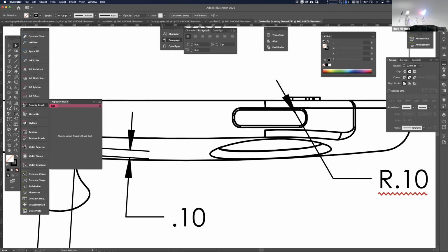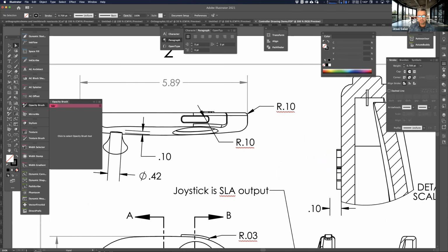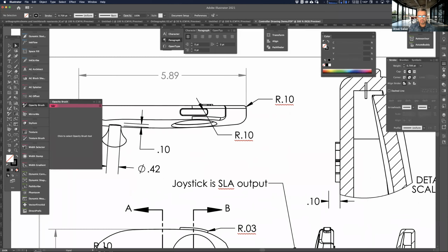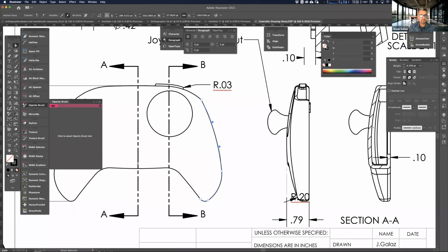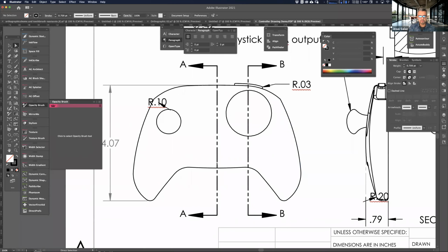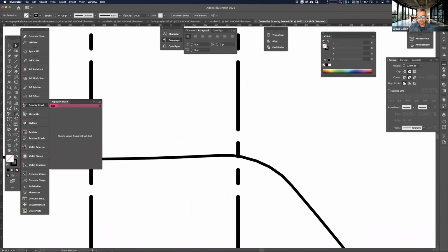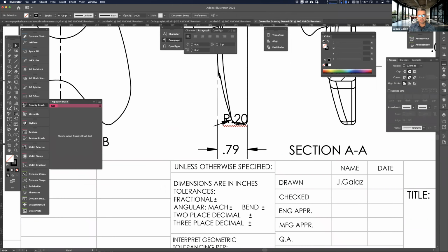So yeah, the topic here being able to clean up your SolidWorks drawings and getting rid of all this data that you really don't need, all these fillet tangent edges, and just leaving the ones that you do need. Then cleaning up those edges, making them smoother, using the simplify tool to make these round elements actually round instead of faceted elements, and then joining them with other things. So it works on that.